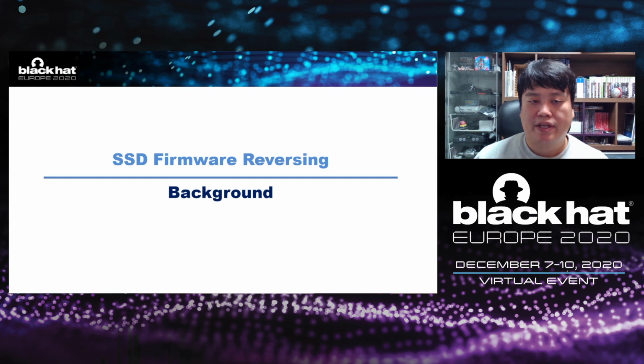I'm going to split this talk about SSD format reversing into three sections. First, I'll explain background information shortly about SSD hardware architecture and the security encoder. Second is SSD format reversing, focused on how to access physical block data, but also it gives prior knowledge which is needed to restore overwritten data on SSD. Finally, I will show you how we can recover the overwritten data if there is a hardware-based security encoder.